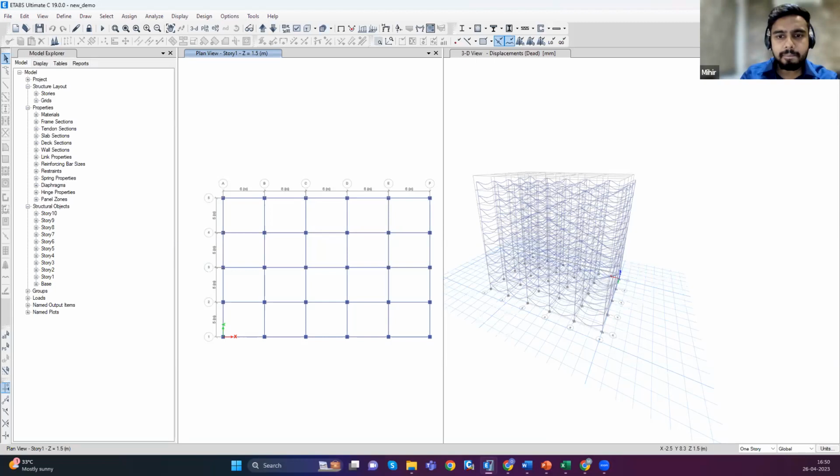Okay. And there is a question which says: what will be the effect on the pushover curve if the columns are modeled as a lumped plasticity hinge? So the question is more related to a modeling strategy. Suppose you change the modeling approach, if you choose a different kind of model, maybe a fiber hinge model or a lumped plasticity model, do you think there will be a significant impact on the shape and the properties of the pushover curve?